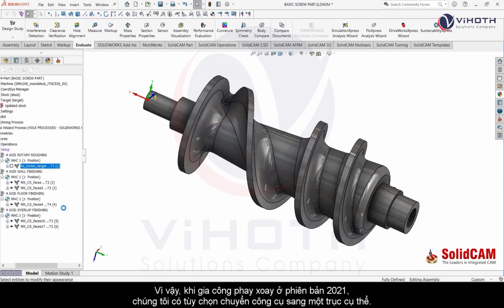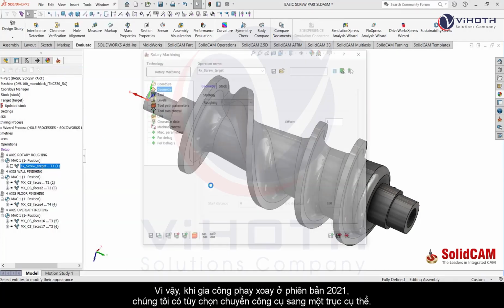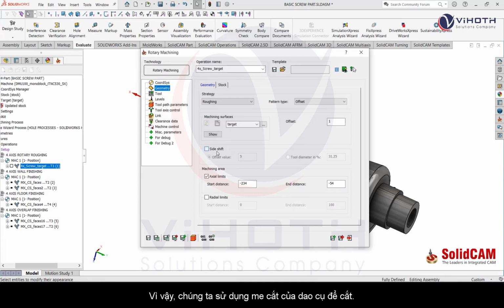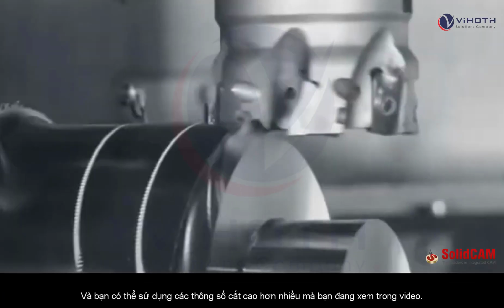So in 2021 Rotary Machining, we have got an option of shifting the tool in a particular axis so that we use the side of the tool to do the cutting. In the video that you're going to see now, you can see the effect of moving the tool away from the center and cutting it. The material removal gets improved dramatically. You get a much more stable cutting, and you can use much higher cutting parameters, which you're going to watch in the video.